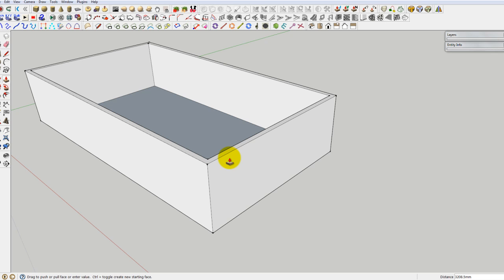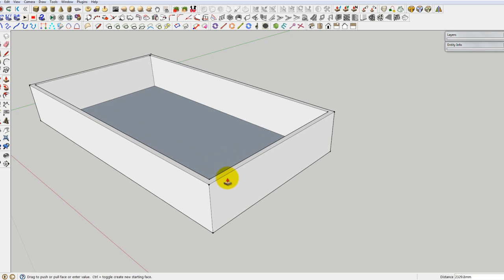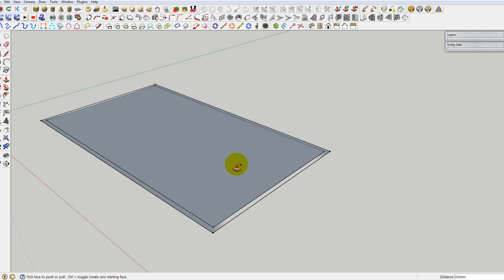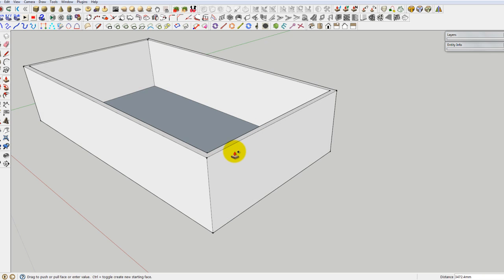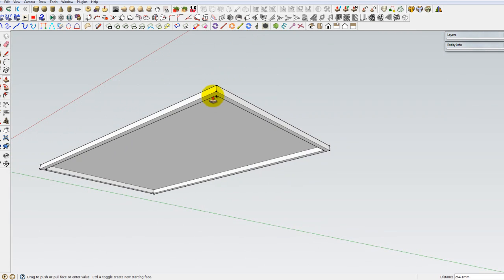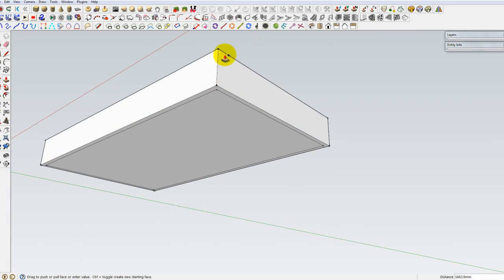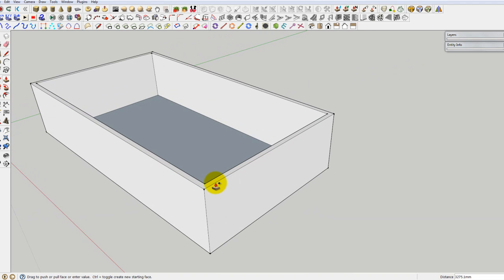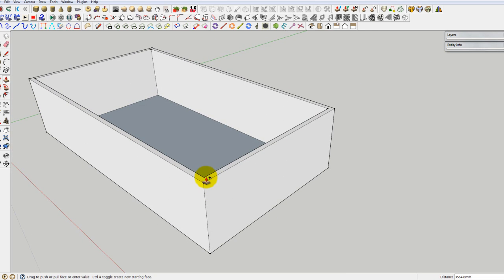So just for the safer side, for always keeping a closed surface, a closed plane, I'll just press Control so that both of the sides have surfaces, right? You can see a surface below as well as the surface on the top. So from here you can just enter the value directly. That would be 3000 mm for me.